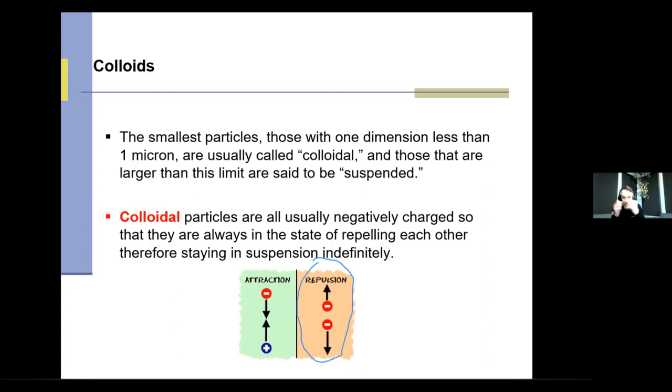It has not separated. And that's because it doesn't stop. It's always moving. The particles are always repelling each other. And so under a microscope, all these little particles are repelling each other because they're all negatively charged. And that's a problem. So how are you going to settle this stuff and get it out of solution when they don't stop moving?